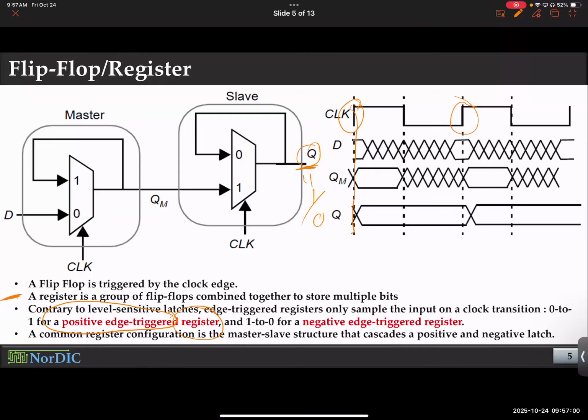That's why it is so important. Clock is used to synchronize things. You can control the clock signal, keep track of how many edges you have sent, and then you can keep track of how many bits have passed. So, hey, I sent 4 clock edges, so you have the row information. Then I send 4 more clock edges, you have the column information. I've sent 1 more clock edge. So you see my point here? Okay. So in a master processor, clock is everything.